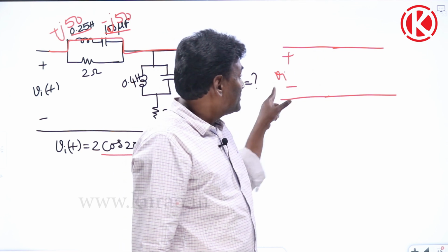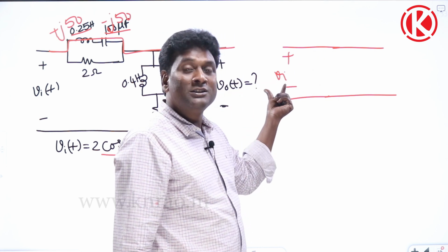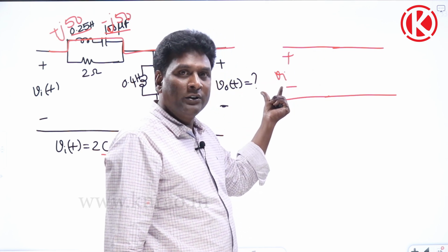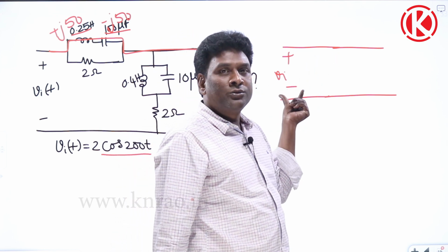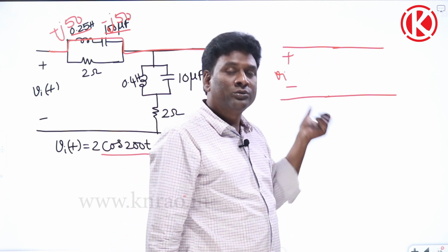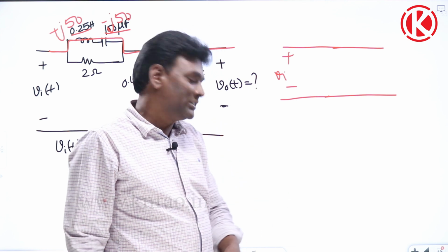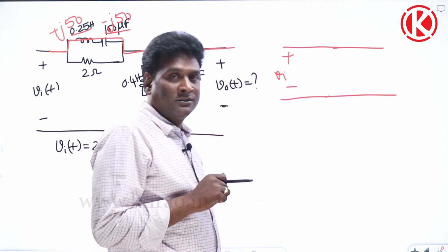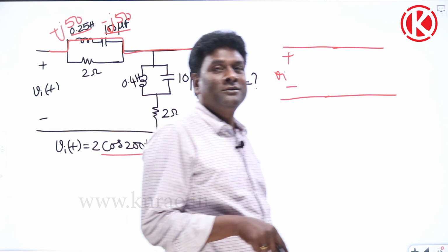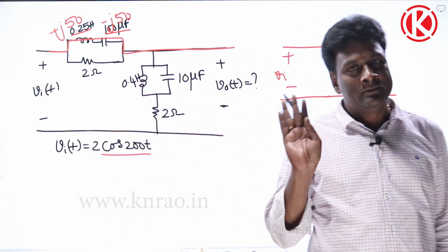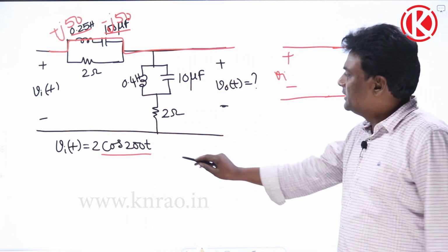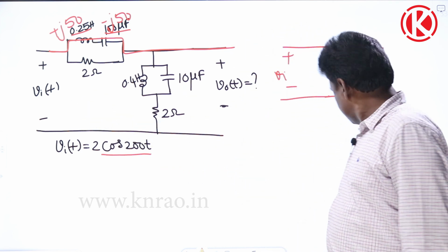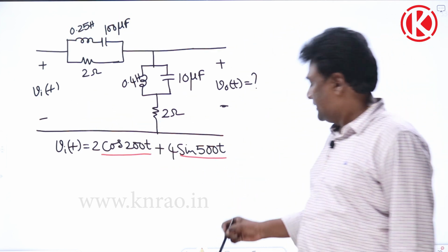But in current calculations or power calculations of this particular source, it will definitely vary. Across an ideal voltage source, the shunt branch can be removed for calculating voltages, for mesh analysis, or for KVL. We discussed that. Now the same input will come.